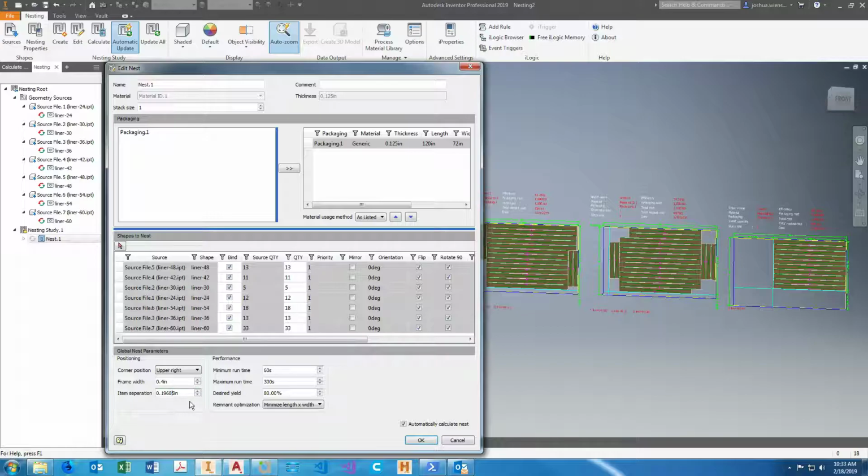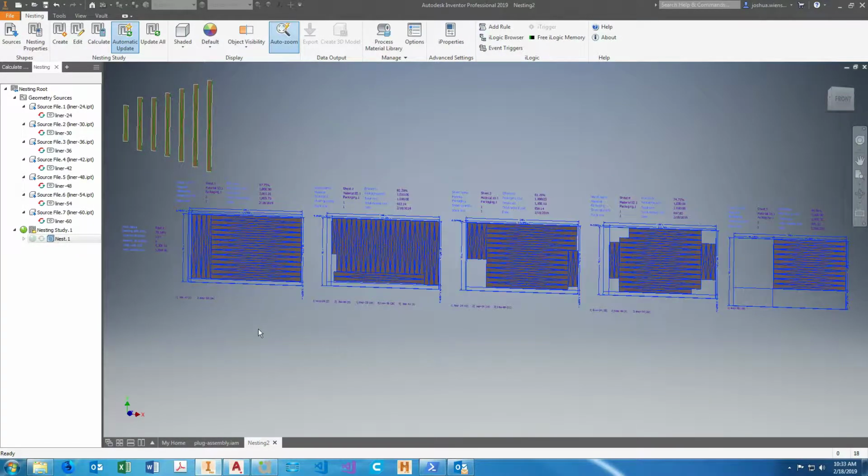But, so I'm using a 9/16 bit, and usually I would make the gap 0.6 inches and just do a full loop around everything, but because all these things are so neat, there's a lot of opportunity to just make one pass, like cut down one line and cut out several pieces. So I actually will make it exactly 9/16 inches. But we'll see here in a second that that actually doesn't work the way you think it's going to, unfortunately.